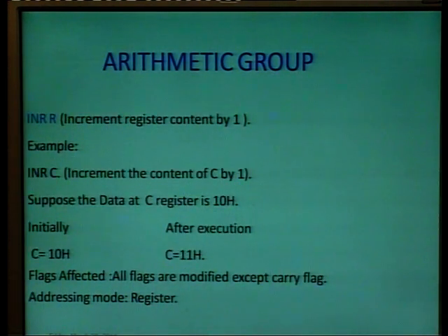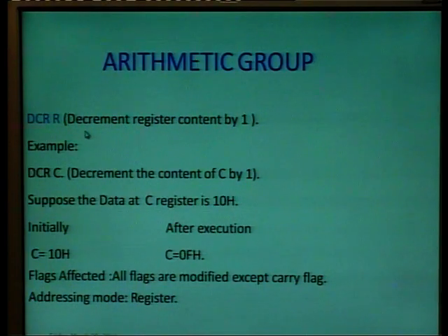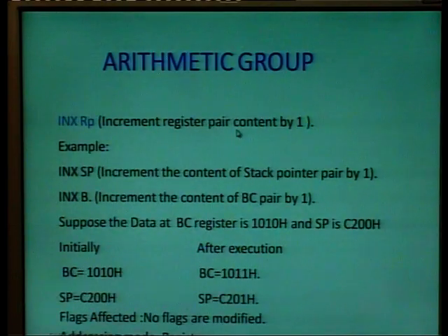Another is INR R. This increments the 8-bit number of the register by 1. DCR decrements the 8-bit number in the register by 1, and INX increments the register pair.